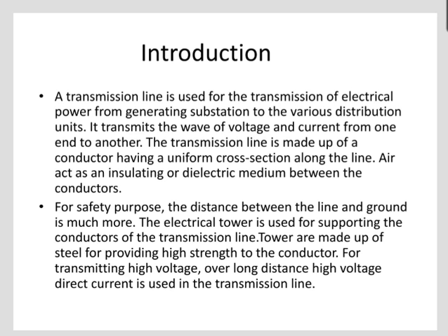High frequency interconnects require special consideration because they often behave not as ordinary wires but rather as a transmission line. In low frequency systems, components are connected by a wire or PCB traces. The resistance of this conductive element is low enough to be negligible in most situations. This aspect of circuit design analysis changes dramatically as the frequency increases.